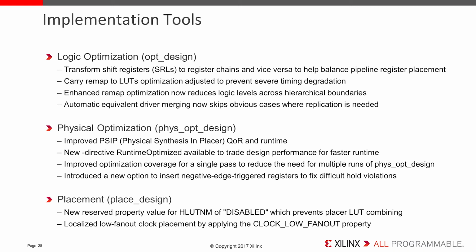Also, using a net property called CLOCK_LOW_FANOUT on a global clock now directs the Placer to confine the buffer and loads in the same clock region. This will eventually be added to the clocking wizard for the safe startup option, but in the meantime, the property can be manually applied.